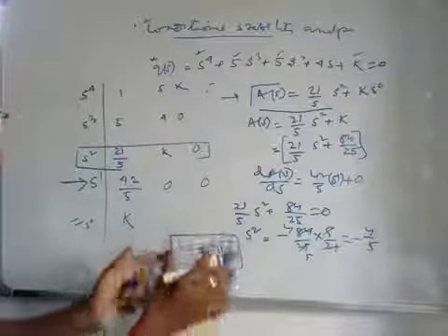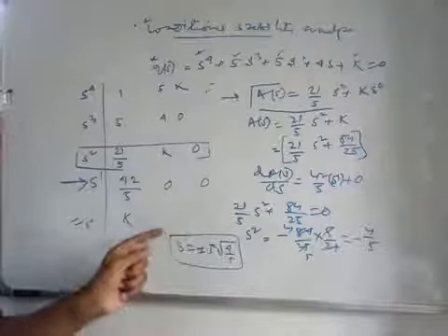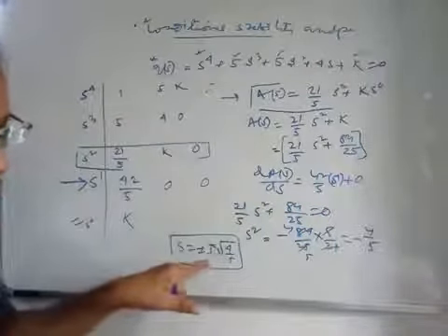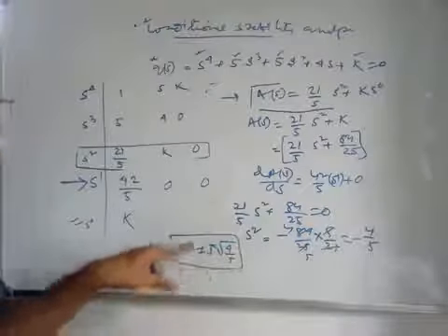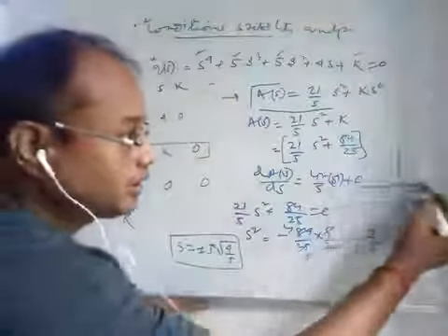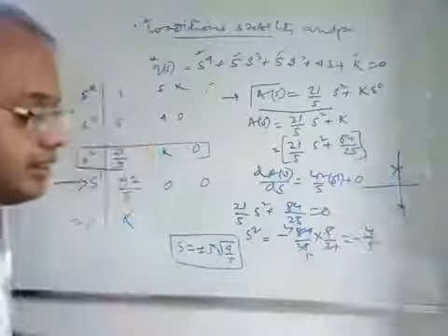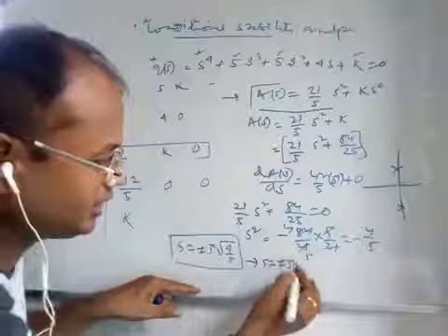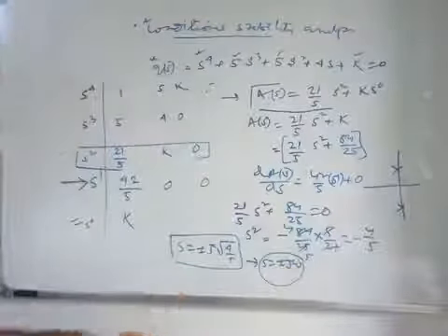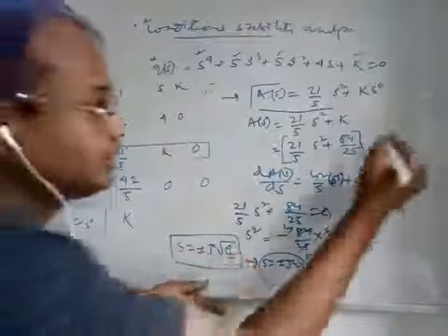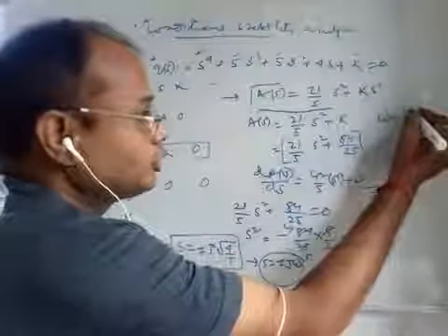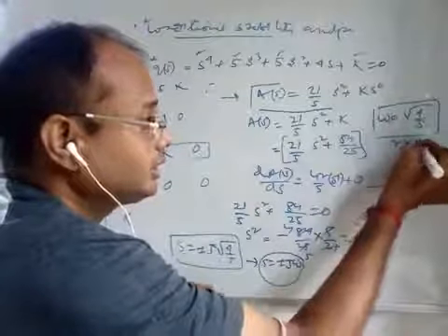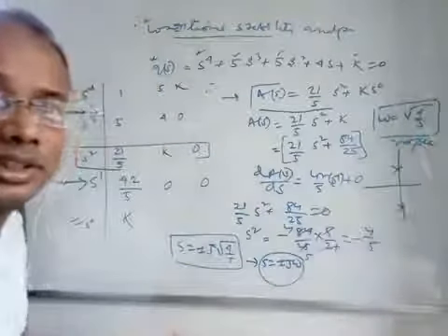So you see marginal stability has been achieved, and the roots have become purely imaginary. So the roots are either here or here. By considering s is equal to plus minus j omega, we see what the frequency of oscillations is. You get frequency equal to root over 4 by 5 in radians per second, right?